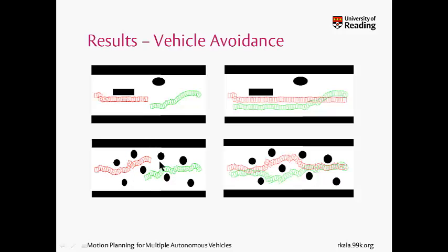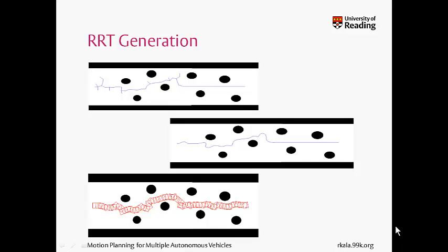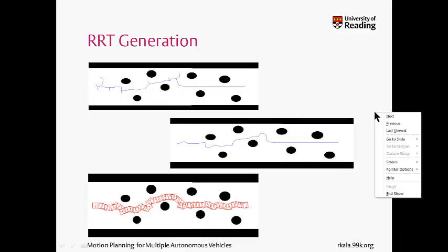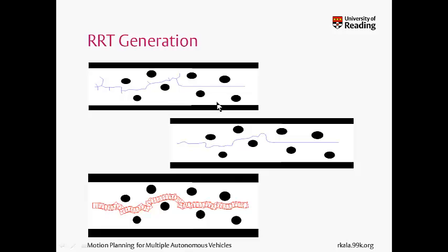The good thing is like this, the first vehicle came here, the second vehicle knew it cannot go in from this direction, so it instead went in from the other direction. And again, this is the actual RRT generated. As pointed out, the generation happened only till here, after which straight to the goal path was possible. This is the smoothened trajectory after local optimization technique, and this is the trajectory that the vehicle traces.